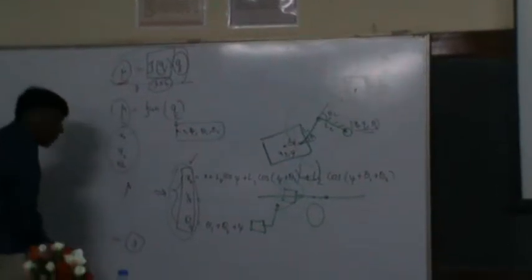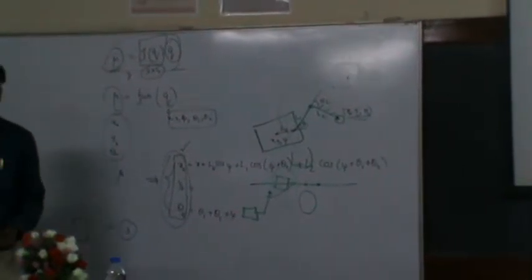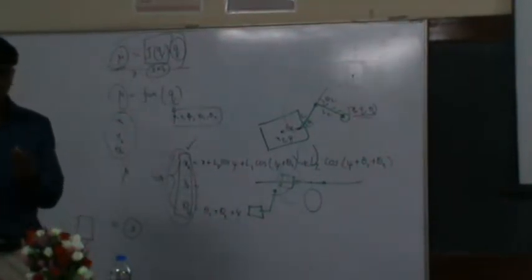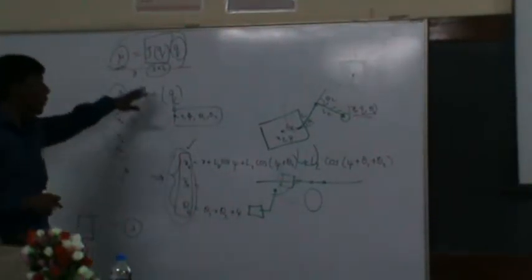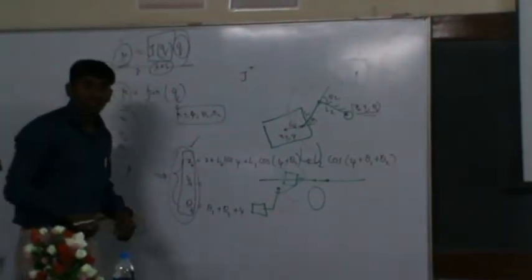Right now, what is our focus? Our focus is to follow this. Indirectly, we will be knowing this velocity and acceleration. So indirectly, you have 3 known and you are trying to find 5 unknowns with the help of the Jacobian matrix. One of the easiest ways is to use the pseudo inverse.